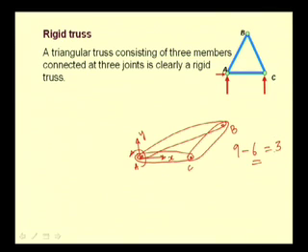So, these 3 degrees of freedom have to be arrested by external supports, and that is what we see, that at A we put a pin connection. So, thereby it offers both reaction components AY and AX to arrest any translation, and the rotation degree of freedom is arrested by providing a roller at C.